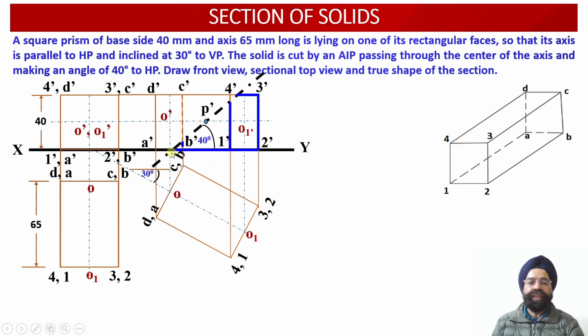So once we know that this is the remaining solid which is left behind after the sectioning of this inclined square prism over here, now we are required to evaluate the points of intersection which this cutting plane will be providing us onto this inclined square prism. Now we can check the first points which are available with us. They are lying onto the base.